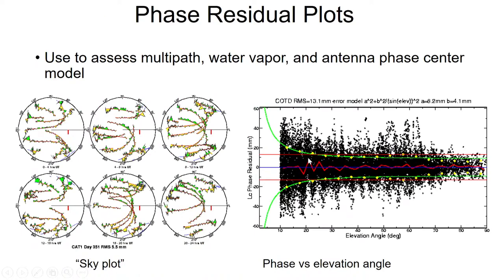And this is the error modeling and error visualization, how much error is associated with the data after the completion of the processing. You can see at low elevation angle it has a little bit more error, but when you go for high elevation angle, like this is 90 degree, you can see the error is reducing, it is constrained between these two ranges. This is the uniqueness of GAMIT processing, which after so many steps creates the covariance matrix for error estimation, and then you can visualize how much error is associated with the data.